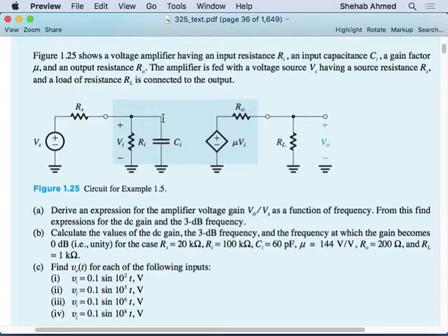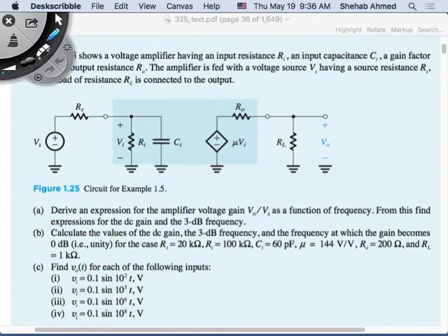So what if I do this? I'm holding this capacitor here, and I'm looking from the nodes of my capacitor into the circuit. I short the source, and I look at the equivalent resistance at these two nodes, like a Thevenin equivalent resistance between these two nodes. What is it? It's these two in parallel, RS times Ri over RS plus Ri. So tau is going to be equal to Ci times the parallel combination of Ri.